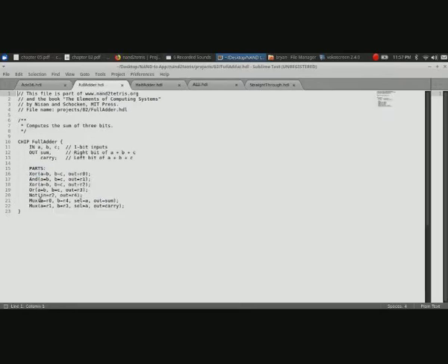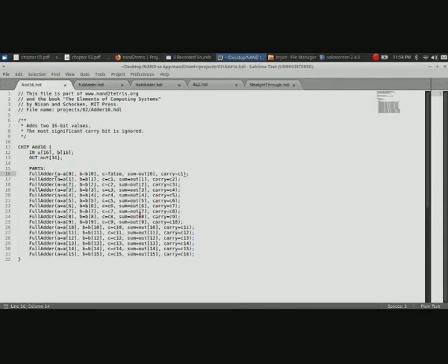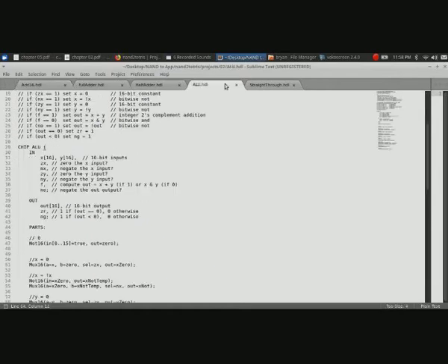You only have the NAND logic gate built in for you, and then you build things like XOR, AND, OR, and NOT gates, and so on. Once you build those, you can use them almost like writing a function. So with the C syntax, you're actually specifying a circuit, and then you load it into their software, and it emulates it and runs it for you.